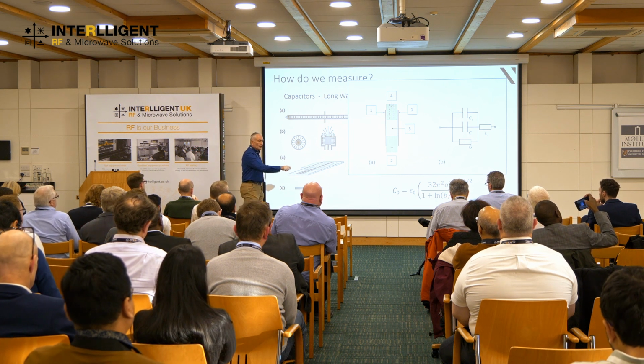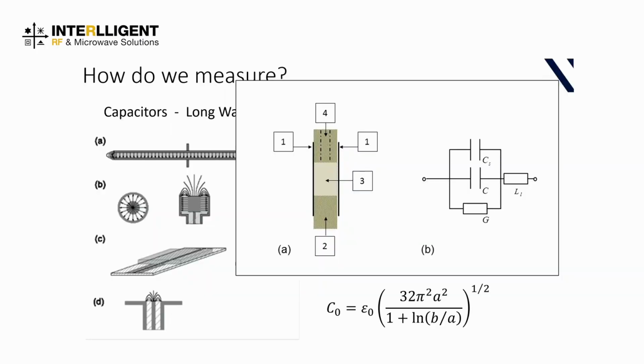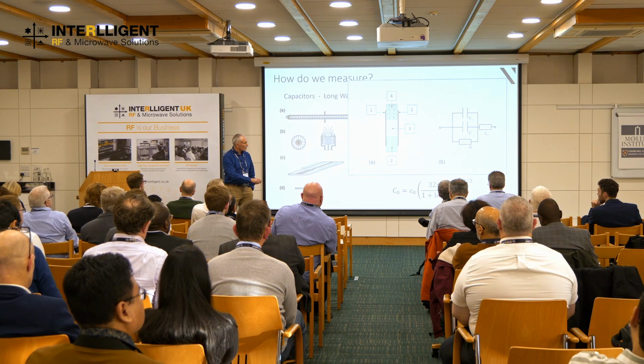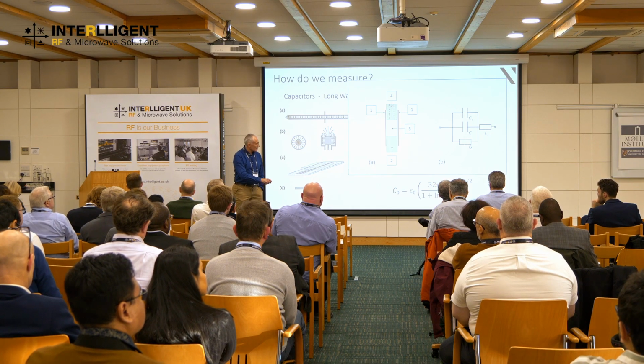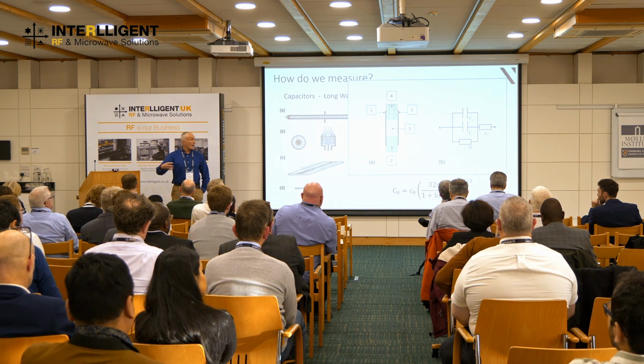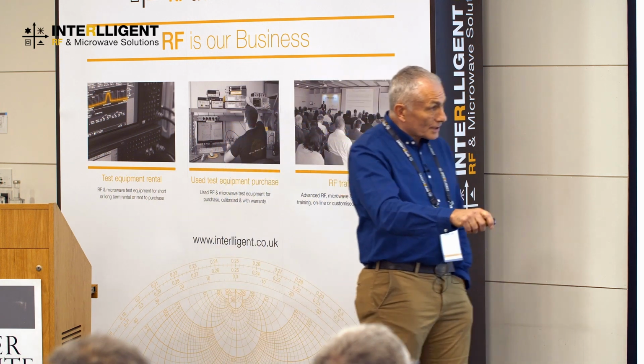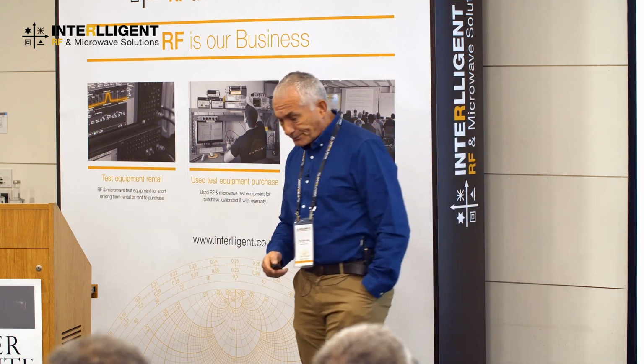This was designed for a flow-through technique, and if I convert that to an electrical model, that's what the electrical model would look like. I've got certain areas I have to take into consideration, where this inductive element and this admittance element account for the measurement line I'm actually using. So you've got to take those into consideration too.